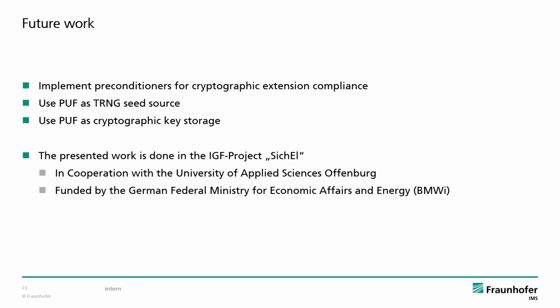During the next month, we will be implementing the signal processing logic to precondition the raw PUF data. Thereby, we will implement an interface that is compatible with the Cryptographic ISA Extension. Because our PUF produces a random value for each input parameter, so-called challenge, we'll test its performance as a seed generator for TRNGs. In the future, we'll work on the stability of the PUF and on error correction mechanisms, so it can be used as a secure key storage element and in challenge response-based protocols for authentication.